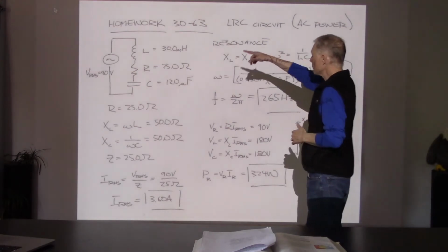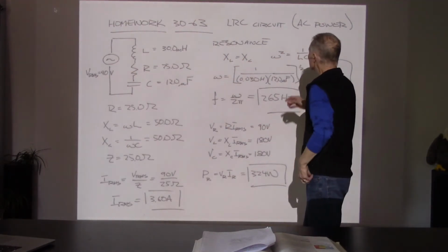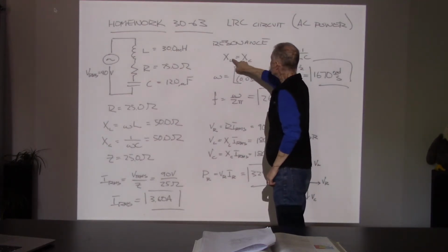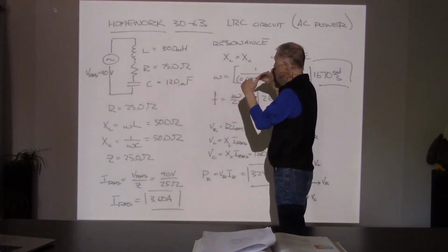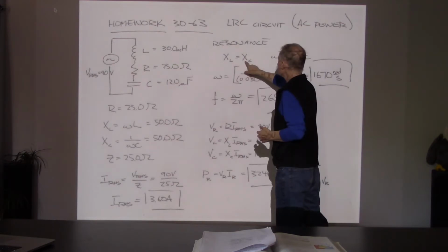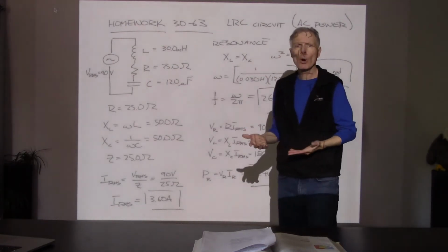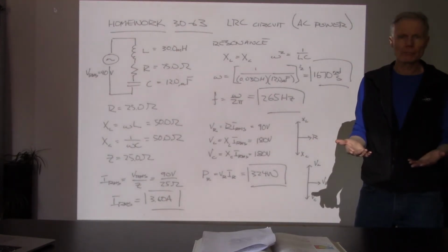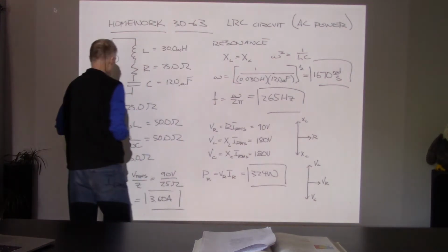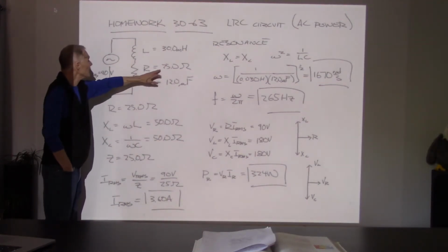And for a particular set of L, R, and C, what we can do is set up what we call resonance. Resonance would say that at a particular frequency, given by XL equal to XC, we can minimize the overall impedance. So we're trying to get Z to be as small as possible. Now the smallest Z can ever be is equal to R.